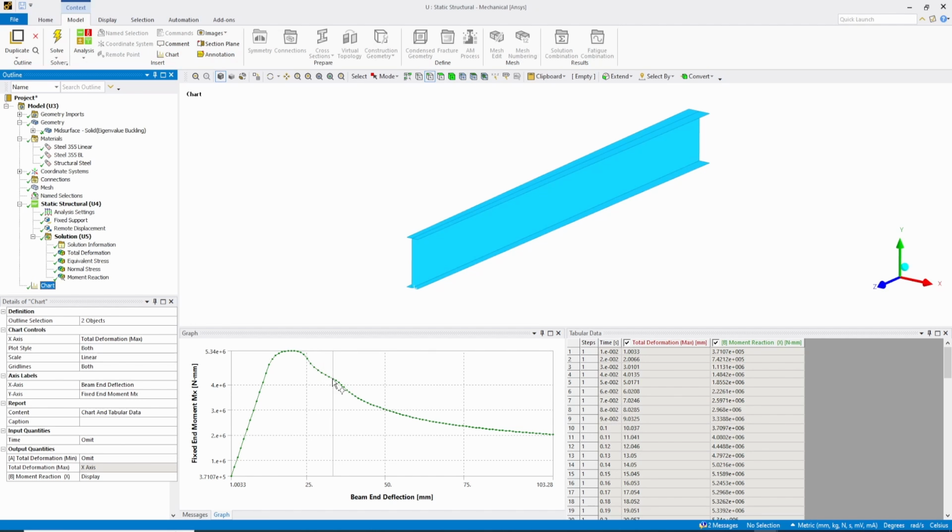You can see the two waves here, and after that the load bearing capacity of the beam just drops significantly, unlike the previous charts of shear buckling, where if you recall, we still had a significantly high post-buckled load bearing capacity. So this is going down as I'm applying more and more displacement at this end.